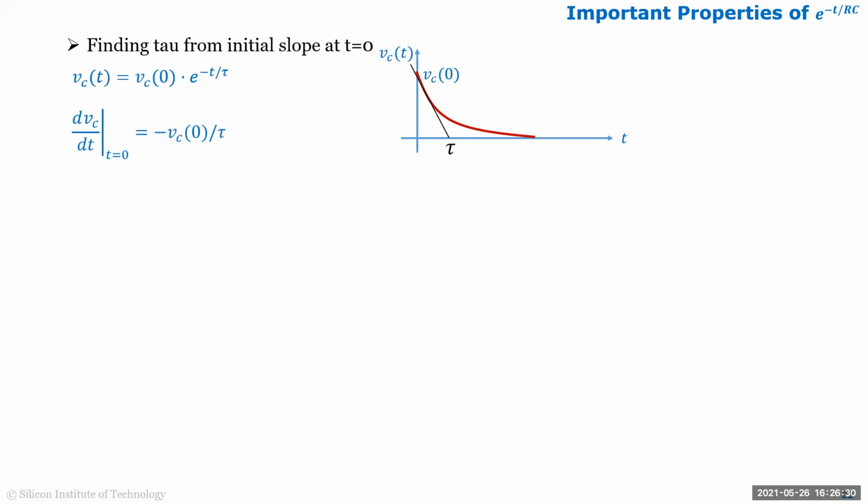And I just want to show quickly some properties of the exponential. So for example, if you know the time domain curve for the discharge, this is how people usually find out experimentally what the tau is. If you know that it is a dominant RC, like there are no series RCs and Elmore RCs and so on, then you find the slope at the point when it starts, at VC of t equals 0.